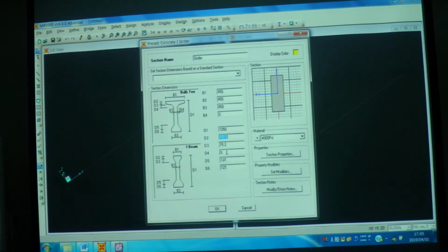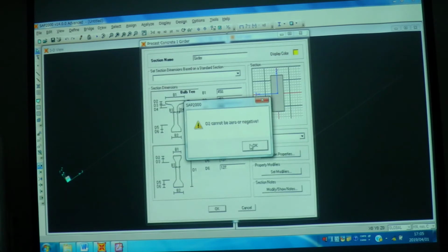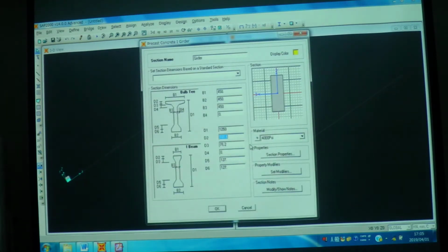There is no need to adjust the other values, even if you make them 0, it is not going to have any effect. This is the rectangular girder. This is the width and this is the depth. So 1 is along the length, 2 is the gravity and 3 is the moment, M3 and V2.